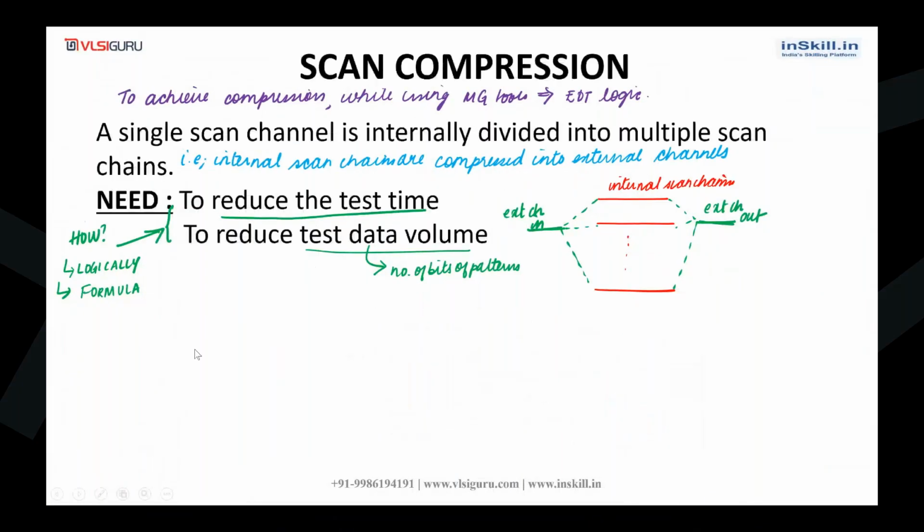Okay, so now let us try to understand this. In order to achieve scan compression, if you are using Mentor Graphics tools, then you need to add a logic called EDT logic. The full form of EDT is embedded deterministic test.